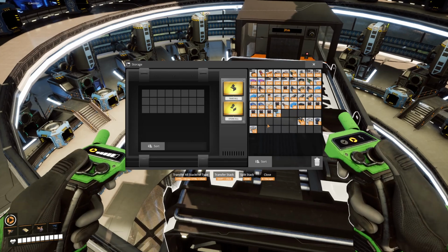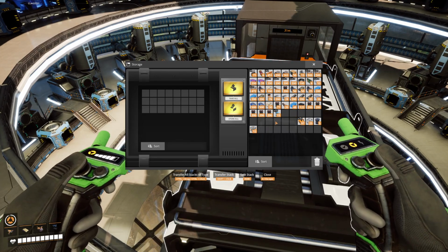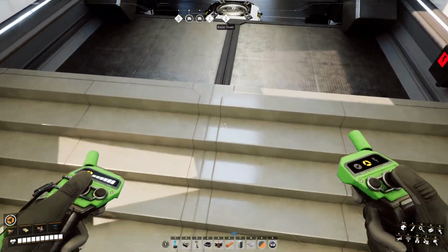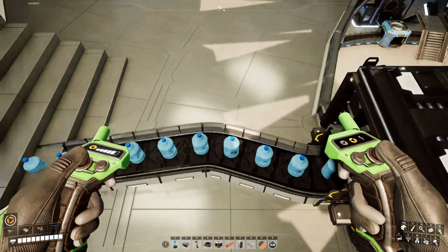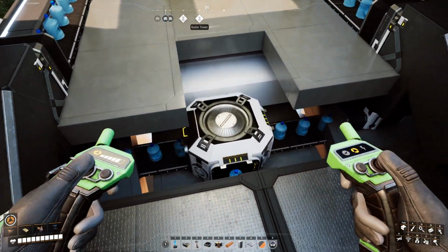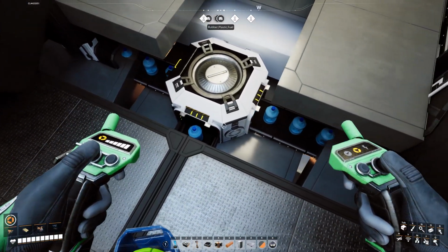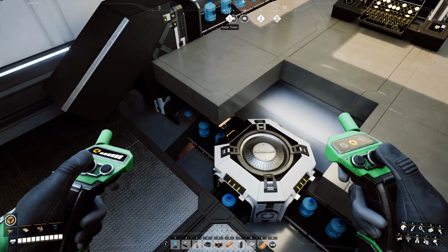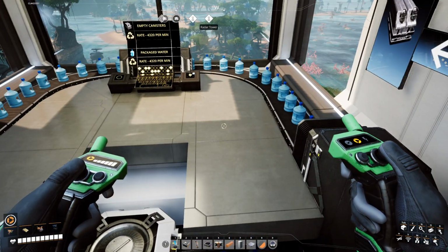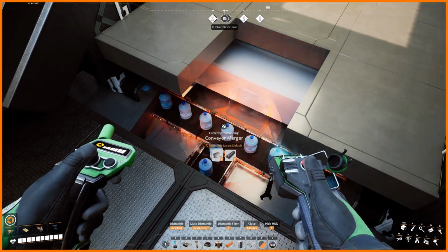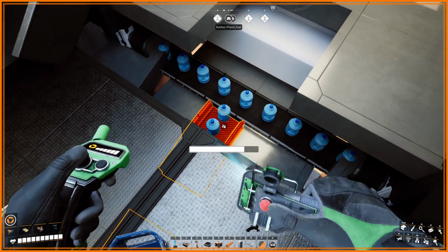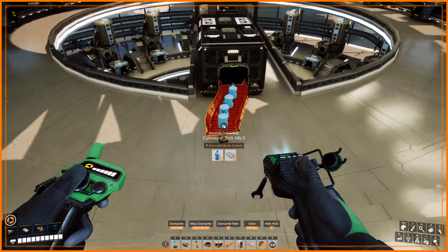And then if we go over here, we're going to take the water, which is over there, and that gets fed into this loop. So the idea is putting too much water, so you oversaturate the line. And then what will happen is it will slowly start filling up. And once the line is full to saturation, you'll see it will stop because it's basically a full line. So at that point, perfect. You can then remove this line that you used to tap into it.